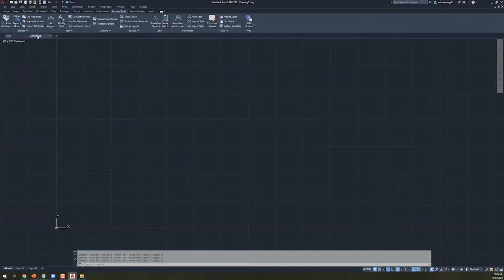And so I think the only other one I would mention over here is probably the Express tools, right? The Express tools are an interesting tab in that there's a lot of experimental and more advanced commands showing up there. For example, arc-align text isn't part of the regular text operations. It's actually a separate command under Express tools. And I've been told in the past that certain commands that exist in the Express Tools toolbar eventually get incorporated into the main program somewhere else.